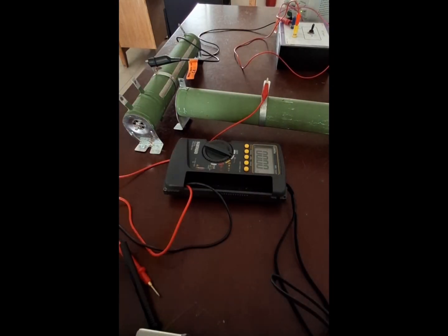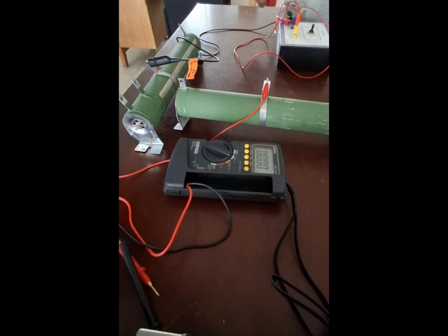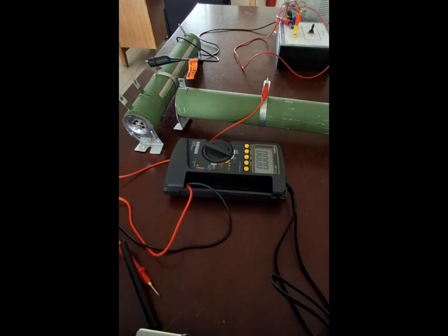So if we sum up the voltages, we get 14.74 volts. I think that's fair, because at this moment we can see that our voltage supply is 14.9 volts, though we started with 15 volts. The voltage supply sometimes goes up and down, so we can see some changes in our values, but we can accept 14.7 volts, and we will definitely see some difference between the supplied voltage and the measured voltage.